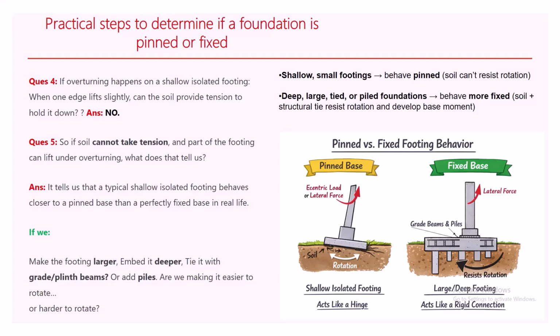Just like I've mentioned before, some of the buildings without plinth beams or grade beams, which is your foundation beam, tend to stand up to date. I'm saying that one of the reasons is that the backfill is also doing something to your foundation. Some of these backfills make the foundation partially fixed and not completely pinned.